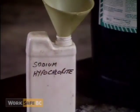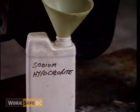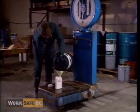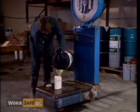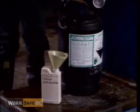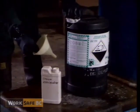Exceptions to this rule are portable containers filled directly from a labeled container. They will have to be under the control of the worker who transferred the product to the new container for use on the same shift. In this case, a means of identifying the contents of the container will do.